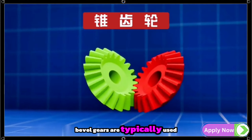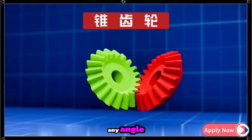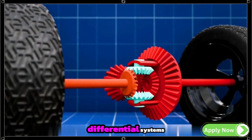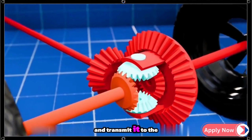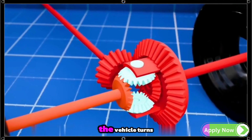Bevel gears are typically used. These gears are conical in shape, with teeth cut on the conical surface. They can connect shafts at any angle, but are most commonly used when shafts intersect at 90 degrees. A common application of bevel gears is in automotive differential systems. There, they receive power from the engine and transmit it to the vehicle's wheels. The differential mechanism allows tires to rotate at different speeds. This is particularly useful when the vehicle turns.